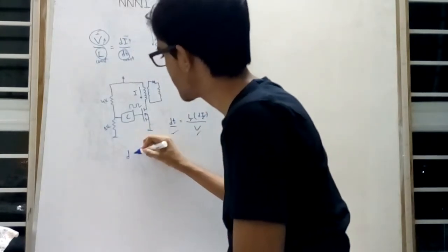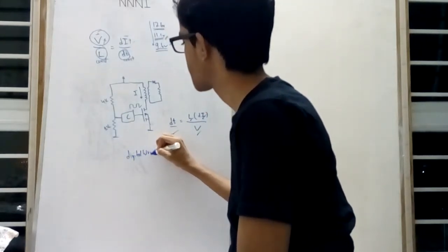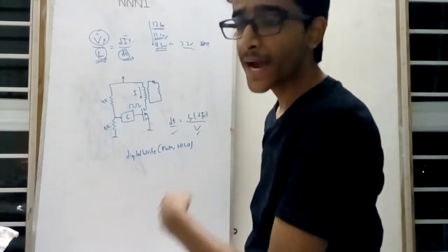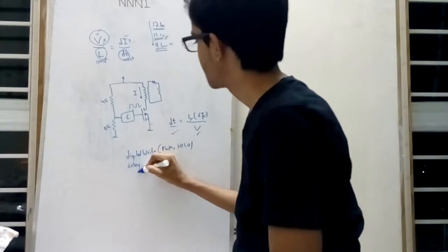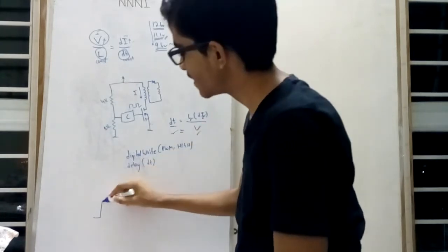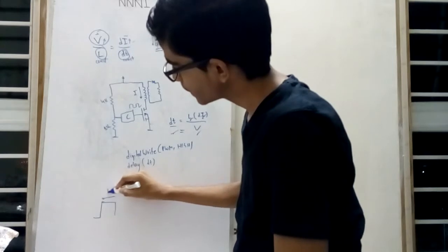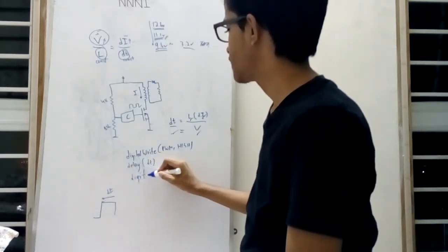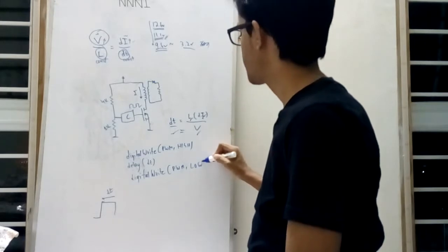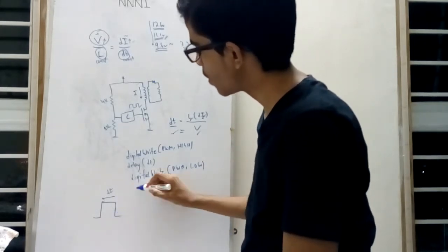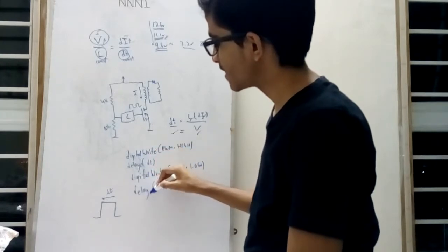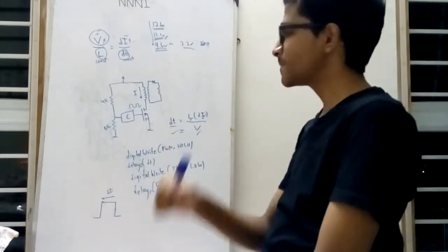Now you could just simply do this if you are using an Arduino. This is a bad method. So you first turn the PWM signal on, you set up a delay dt depending on the value calculated here, and you digitalWrite PWM low. So you turn the PWM off, and then you can have an arbitrary delay. And now over here, microseconds or whatever you've programmed your Arduino to do. So this is basically how my solution works.